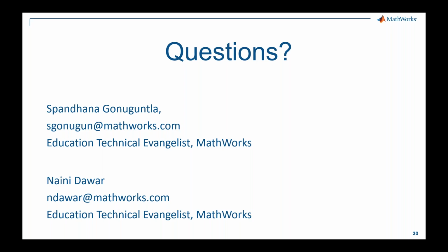Okay, another question from Hemant. Is there a means to perform data analysis offline if there is a loss of internet connection? Yes, you can download the ThingSpeak data directly, or you can stream data into MATLAB first and then move it into ThingSpeak. So if there is a loss of internet connection at any point, you can download the data and perform the analysis offline. That facility is available. I can send in more resources in a web link on how that can be done. I think there is an example as well in my presentation.